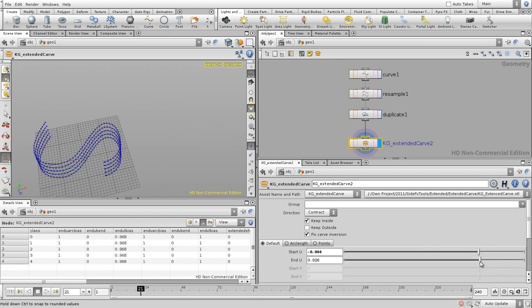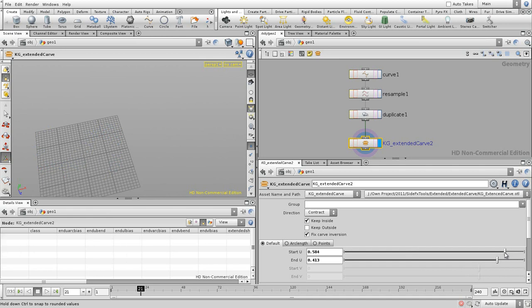so you have the U value or the V value. Now there's something over here which is Set Fixed Carve Inversion. What this allows you to do is, when your carving becomes smaller than 0, it's not going to go to the opposite side, it's going to keep it at a minimum. So this is useful in procedural systems. For the rest, these are quite similar.